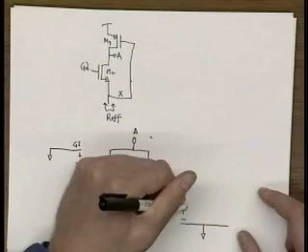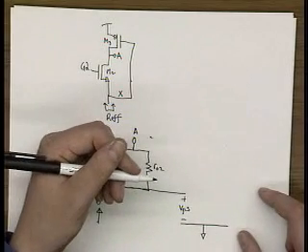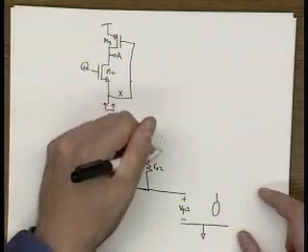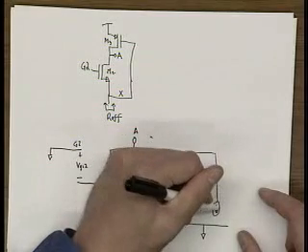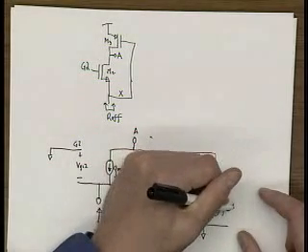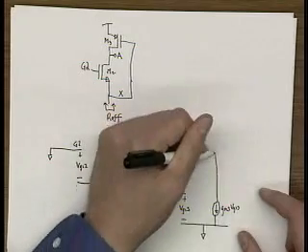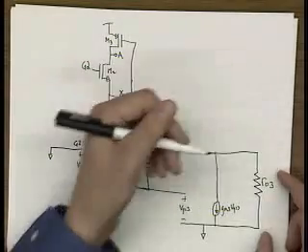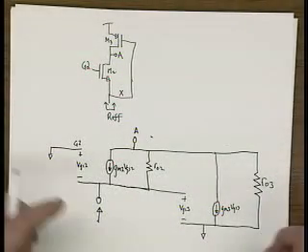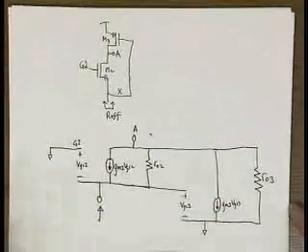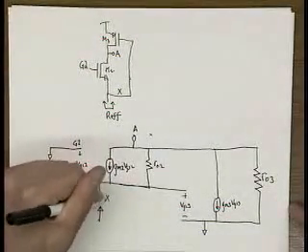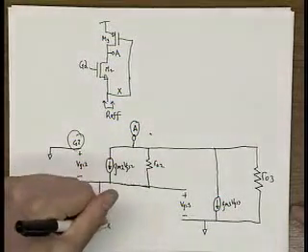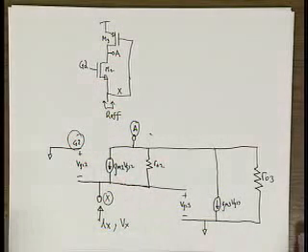There's a current flowing from the drain, which is node A, and similarly, there's that. Okay? This is the small signal model. And then in here, this is node X, node A, node G2. We're going to be inserting a test current IX and measuring VX. Okay?